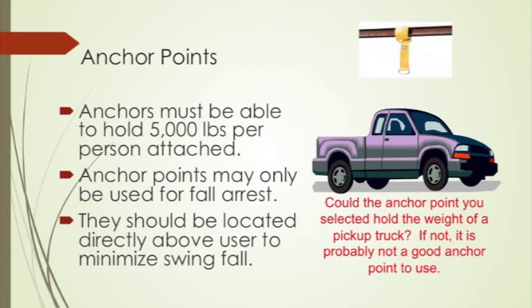Anchors must be able to hold 5,000 pounds per person attached, which is about the weight of a pickup truck. Anchor points may only be used for fall arrest, and they should be located directly above the user to minimize swing fall, as this can cause employees to strike objects near them in a fall. This should be avoided by ensuring that the anchor point is directly above the worker.